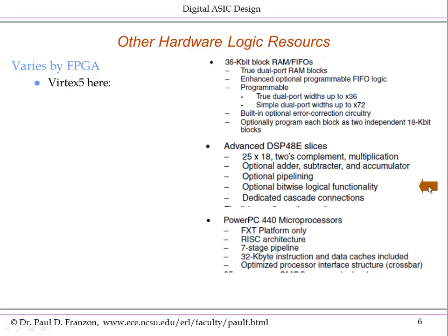And use it very directly with knowledge that these things are available for you, rather than force mappings onto CLBs, which is a lot less efficient in terms of area usage. I mean, this one multiplier is most equivalent in area to a very small number of CLBs. Thus, if you have a multiplier and you can configure it as this 18-bit multiplier, you should do so.